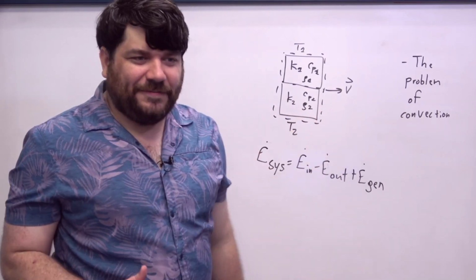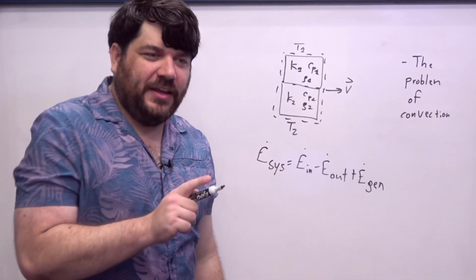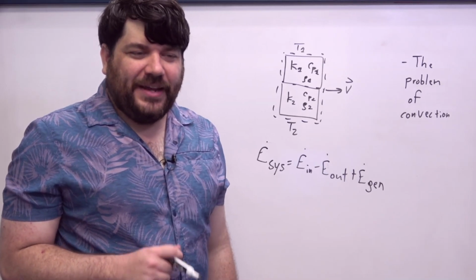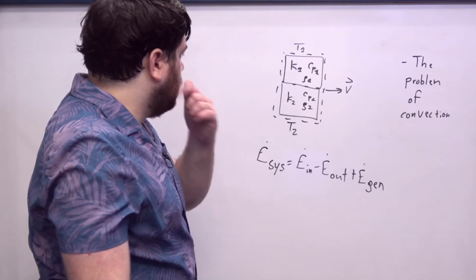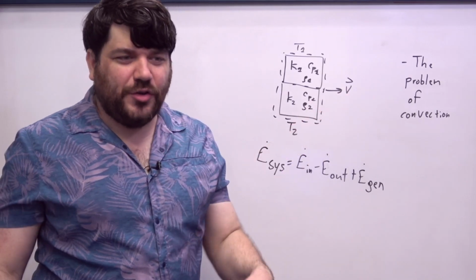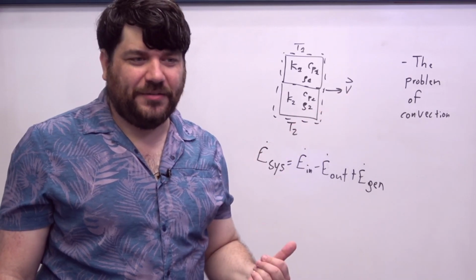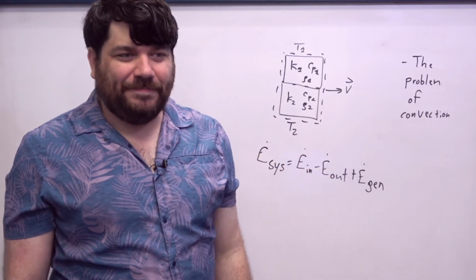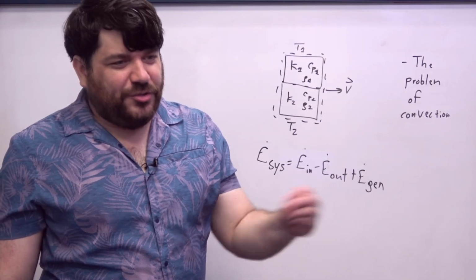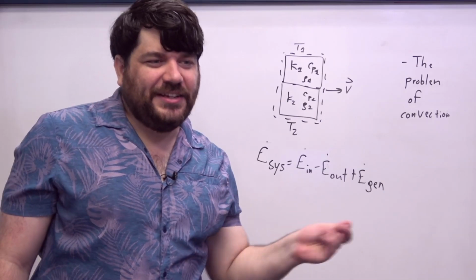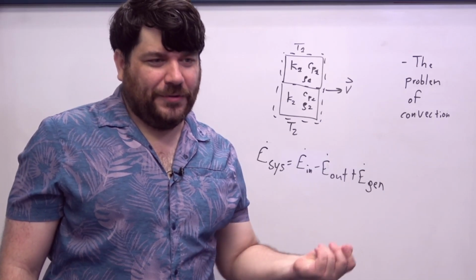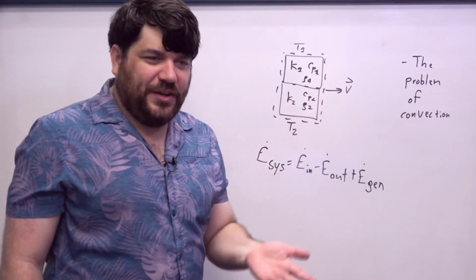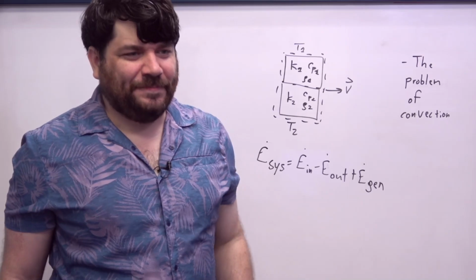The velocity, the kinetic energy of these two objects never factors in to this sort of analysis, right? And the reason for that is because we assume that the kinetic energy plays no role in the thermal development of the object. That even if the kinetic energy were to change over time, that change in the kinetic energy is completely decoupled from the thermal energy changes. And that all of the stuff that involves changes in the kinetic energy is mechanical, right?